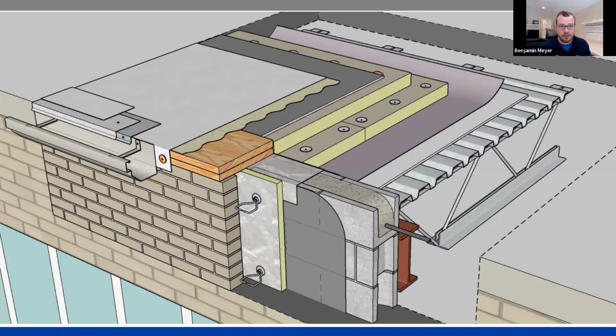So this is a natatorium. There's a pool. There's lots of moisture on the inside. So we have a vapor retarder down at the deck level. But the key then is to tie that into the wall and make sure we're controlling as much to the interior as we can, because it's a pool and it's a continuous source all year long.